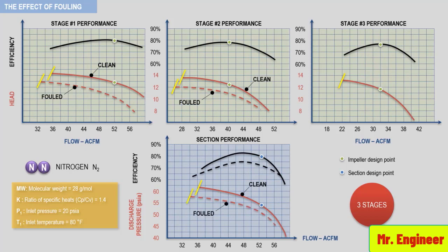Now, since fouling is extremely difficult to predict, I strongly advise you to establish a sort of periodic condition monitoring of your compressor performance. This can provide advance warning to correct compressor internal deficiencies at the first opportunity.